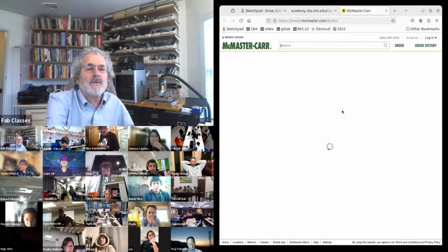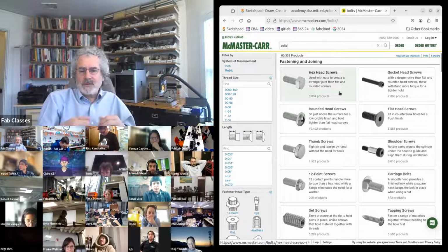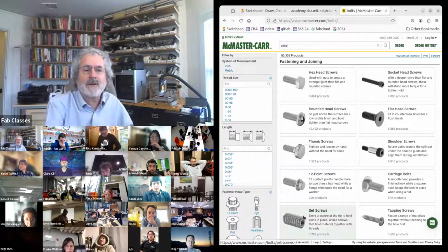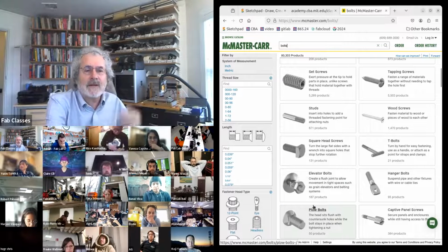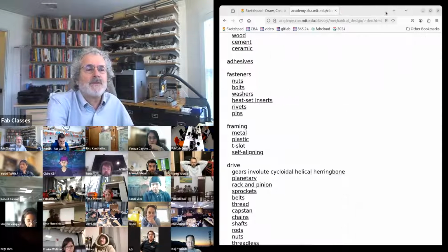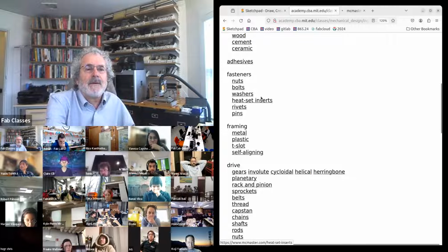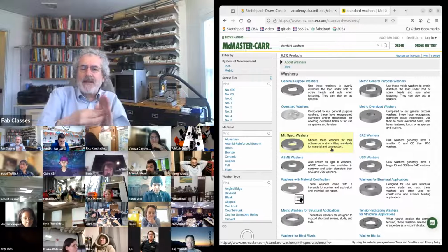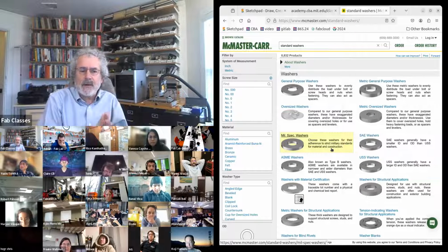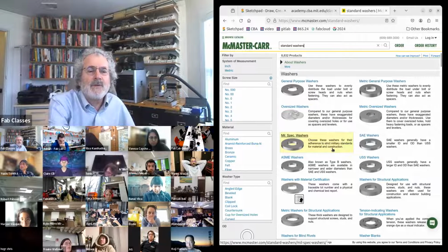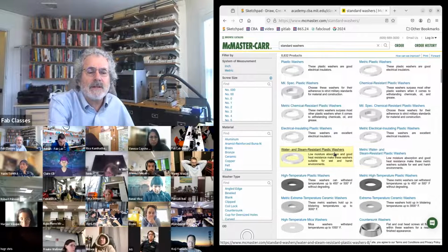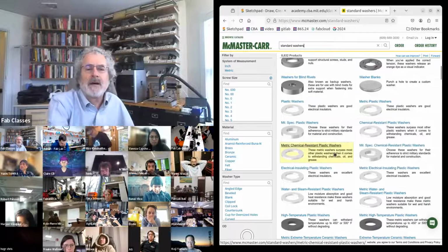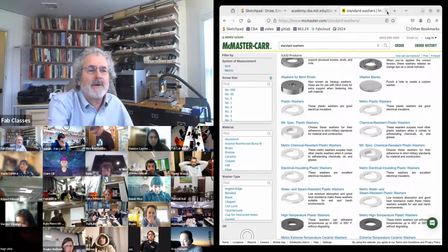For the bolts, we use bolts to attach the machine together. We can use set screws for internal mounts. And then there's more, I'll talk a little bit about threaded rods that we use as motion axes. You need washers when you have something that has to turn against something, like tightening a nut against a load. And then you can also use spring-loaded washers that again prevent nuts and bolts from walking with vibrations.